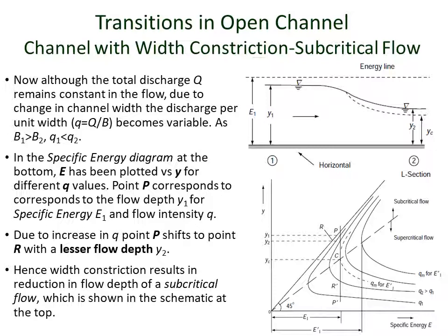The specific energy diagram can of course be drawn for different discharges or different discharge intensities. In the specific energy diagram at the bottom, you can see that different cubic parabolic curves have been drawn with the specific discharge or discharge intensity as a parameter.